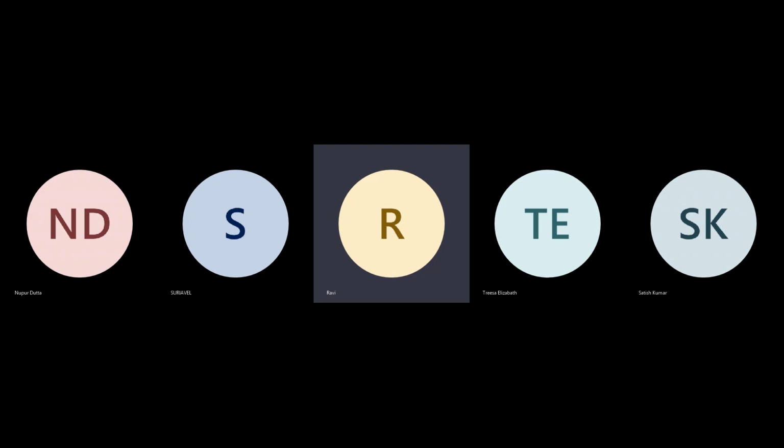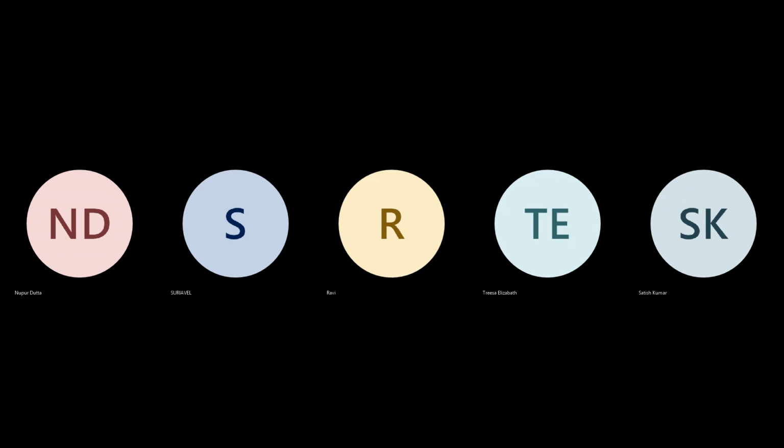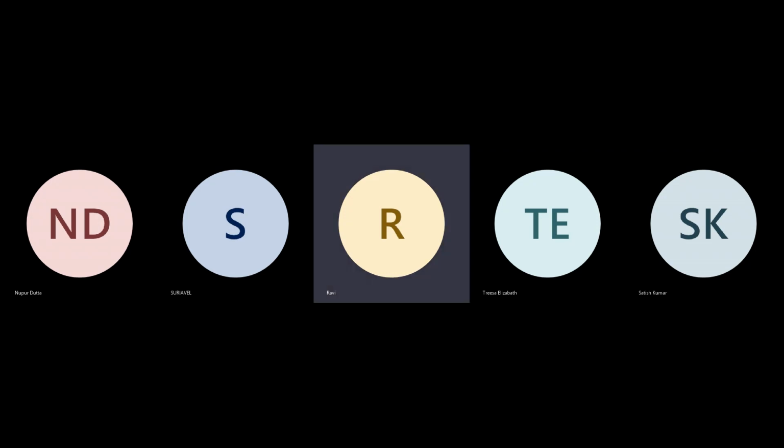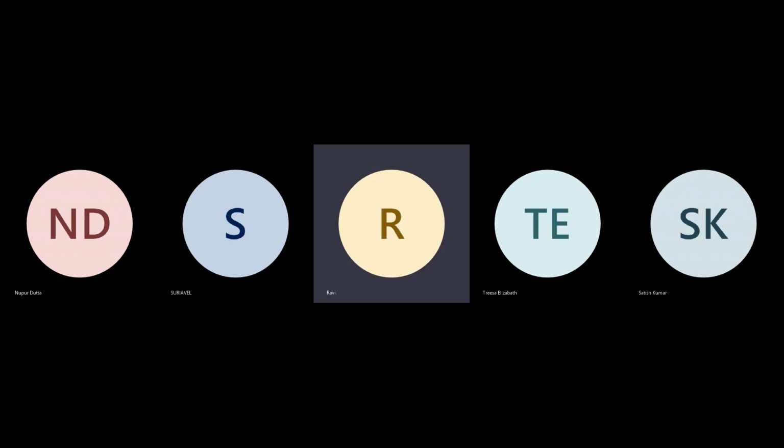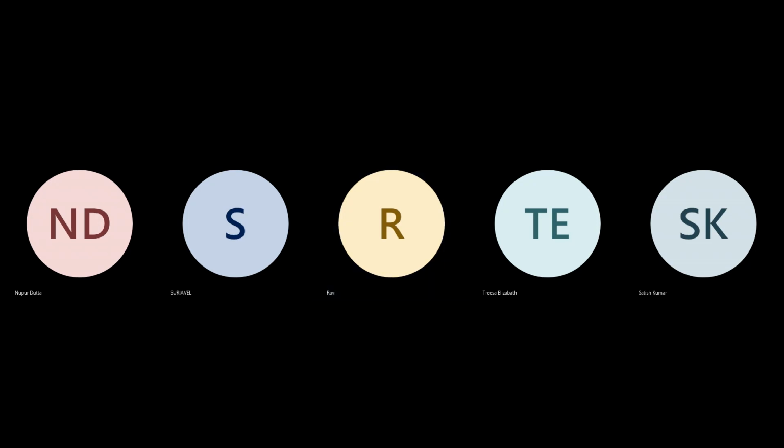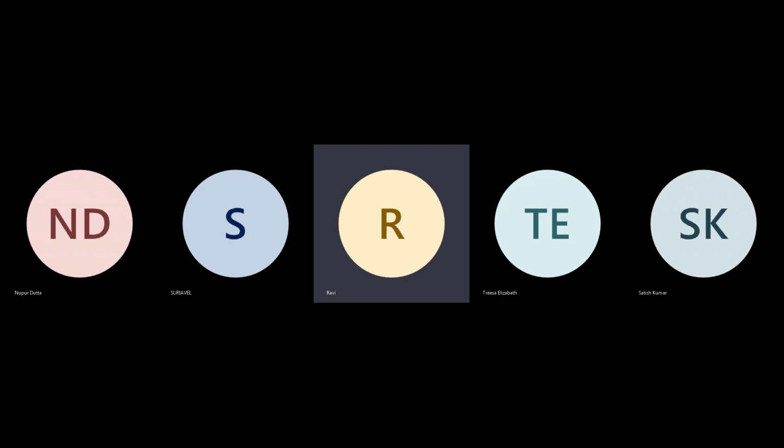You should get mostly at placement stage, even yellow spots are dangerous. Yellow is red for you in placement density. You should get as much blue as possible, and some spots of green. Blue means everything is within 70%, 60% or so. Green is between 70 to 80. Yellow means it's almost 100%. Red means there are actually overlaps, right?